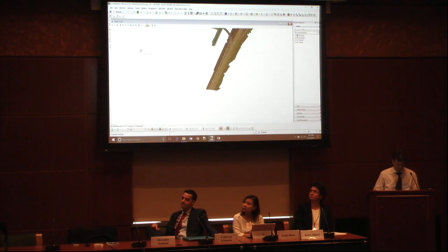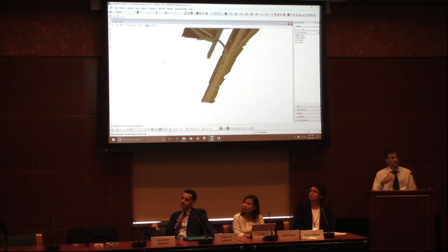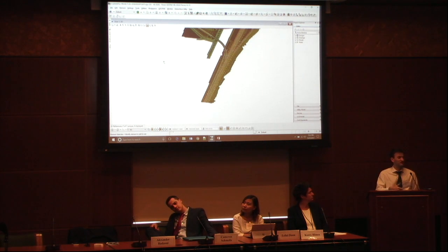It's probably not going to work for me because I don't have full access to the database, but with the parametric constraint, I click on the corner and it lists all the ways I can control that parametrically. Then I switch the pavement over, or the slope, because I changed from what the default setting is. So that's how you can control that mechanism.